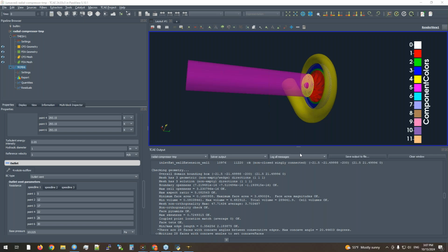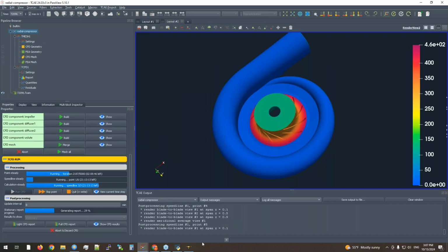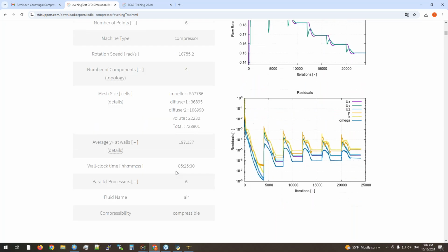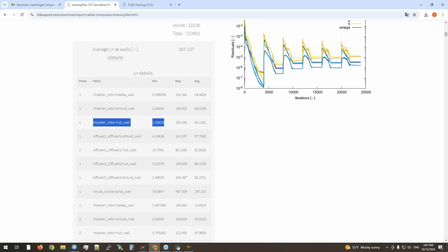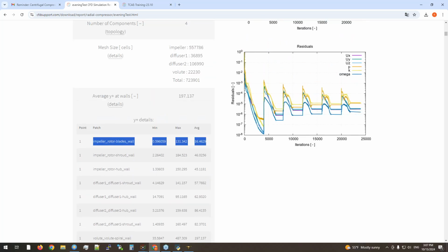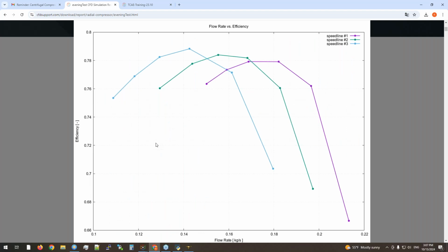Most typically we export the forces: the surface pressure is recomputed to forces, and the forces are prescribed as a boundary condition for the FEA analysis of the structure. For the FEA, Calculix is used, another open source package, and it's a one-way connection. That means a weak connection: if the structure is deformed, the information does not go back to the fluid.